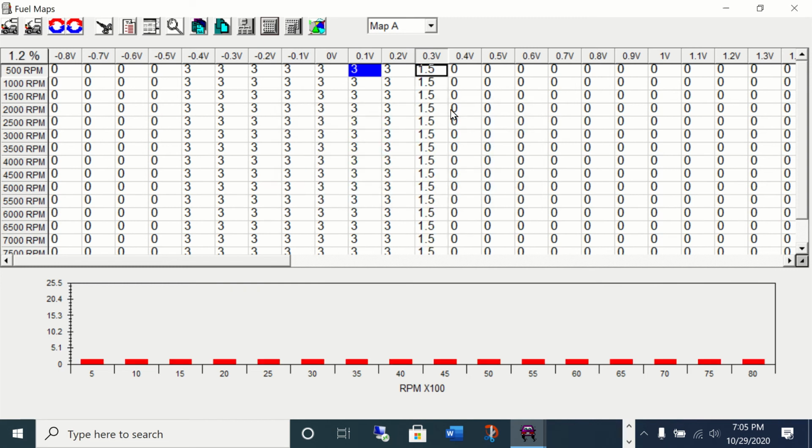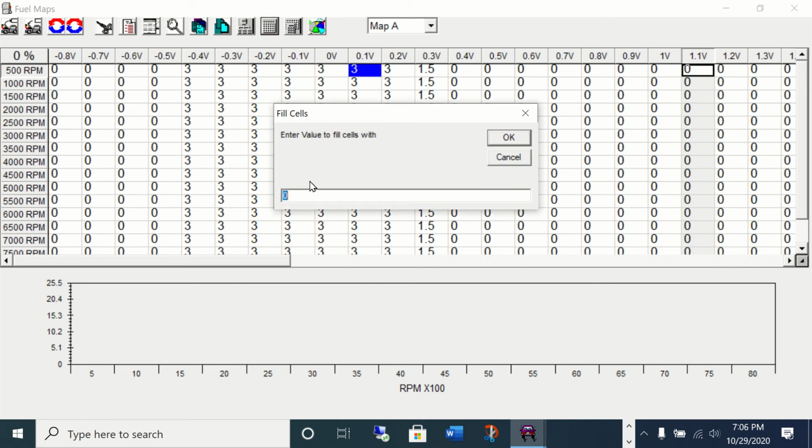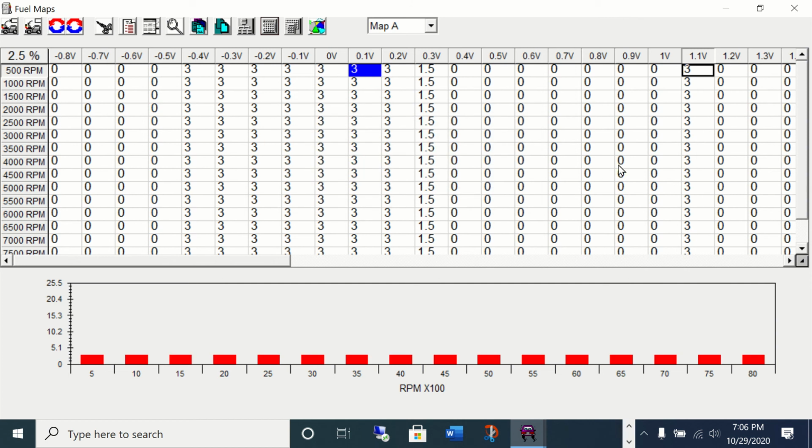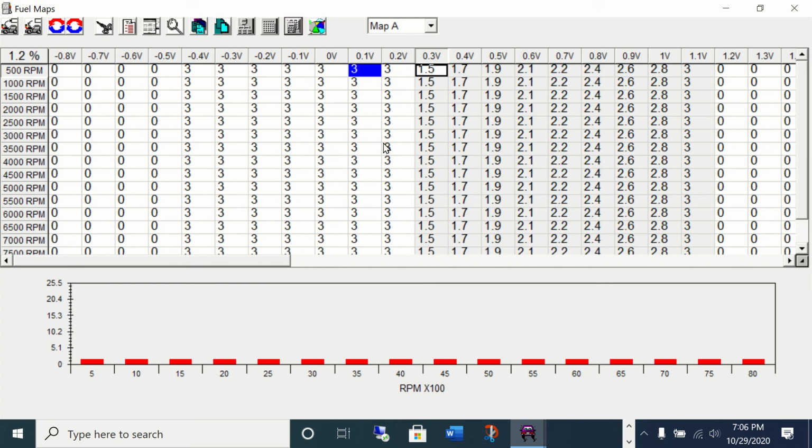And you've got that set up, that's working. And let's say you move over to a higher pressure, you're tuning in this area, and the cell value that works there is a 3. So we'll put a 3 there. And then we don't want to go back and find the right tune for these intermediate values. We'd like to be able to get this map roughed in quickly and get closer to the final value. Well, I can just click and drag, highlight all the columns between these two, autofill, and there we go. It interpolates and fills in the values for us.